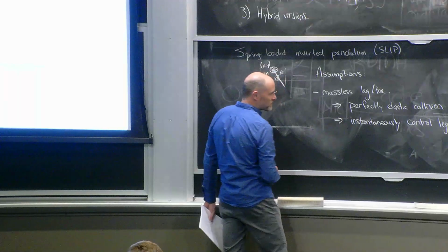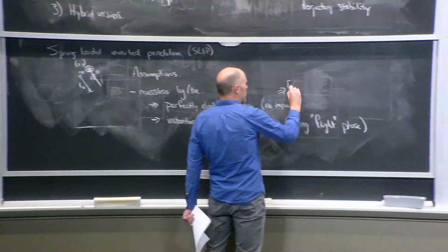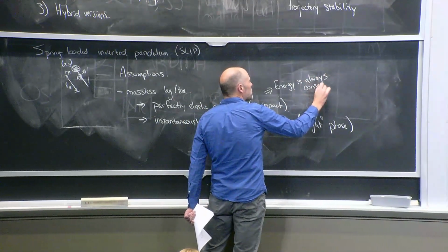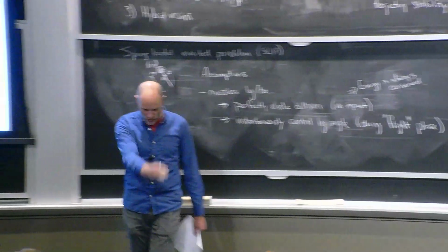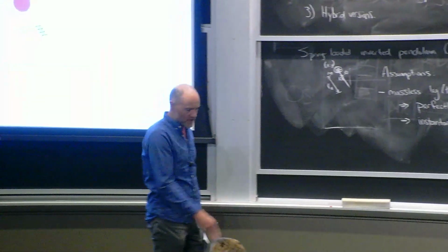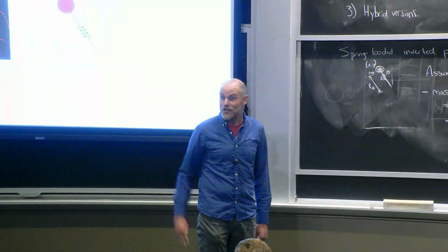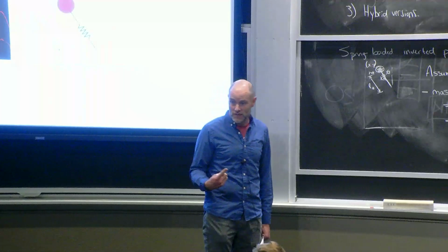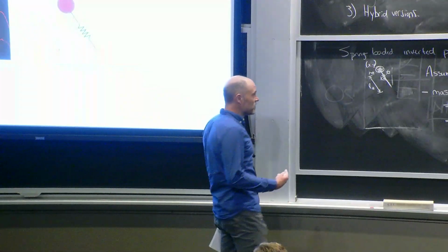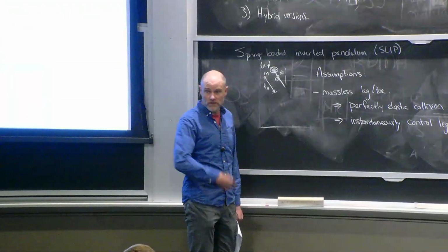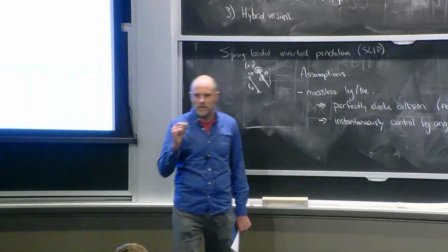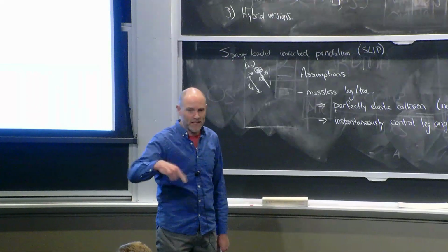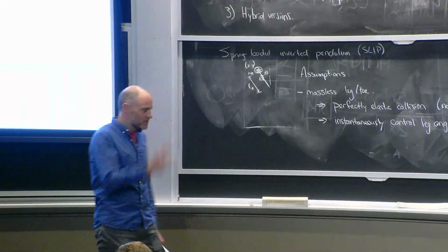And I guess if you have a perfect elastic collision, then the other thing that happens is energy is always conserved in this system. Your actuator, in some sense, is doing no work since it's moving a massless thing around. You're losing no energy at the collision, so you have energy conservation in the total system. Which is a weird thing, because the stability from the rimless wheel came from losing energy. So this thing turns out to have stable limit cycles, almost. It's only stable up to an energy. If you were to push it in a direction that added or removed energy, it will never dissipate that energy to return. So it's only stable up to the manifold of constant energy.